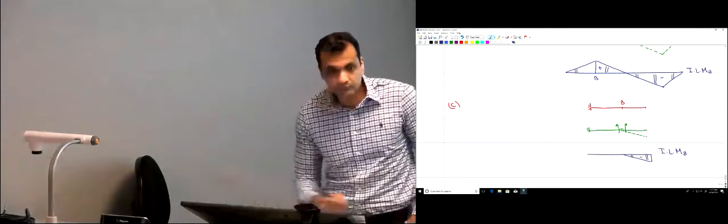Those two parts want to move like this, but actually this part is not going to be able to move up because it's fixed over here. So this is actually going to move like this. That's all. So this is the displaced shape, and it looks the same like the influence line of MB. This is negative. So here, always this angle gets smaller. This theta is less than 180. Try to make this angle smaller. You're applying a positive moment to move them closer to each other.